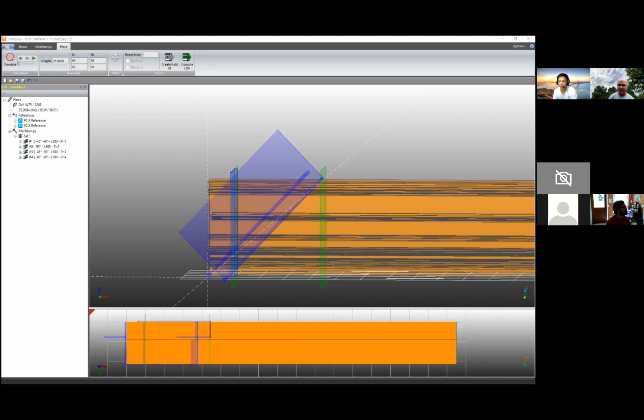No, they are all different machines. We have 3 different types of machines over here. They function kind of the same, but they are all different kinds of CNC machines: 12-axis versus 6-axis versus 3-axis machines. So if I have a miter like this on this machine, I cannot do the same thing on the other one. And like I told you, the DMI can only do horizontal and vertical. It doesn't do any 90-degree cut. So basically you have to reorient the part differently and use different tools to create the notches.